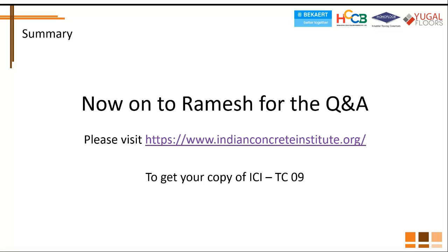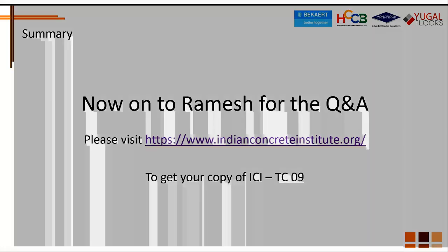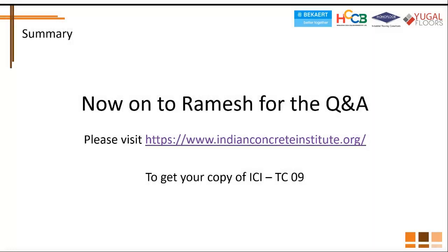Yeah. The problem with corner thickening is that it works like sunken teeth inside the ground slab. It actually becomes a point of restraint, and ground slabs all shrink. Normally it is seen that at the haunches you see some cracking, because that's the point where you have the change of shape. It has been our experience that although it would be the most efficient way to design, constructability is an issue, especially when you want to pour large areas in one go and can't really provide for these variations in the sub-bases. This is also true at the intersection of the joints. You can't do it always, and if your joints are every 4 or 6 meters, this is certainly impractical.